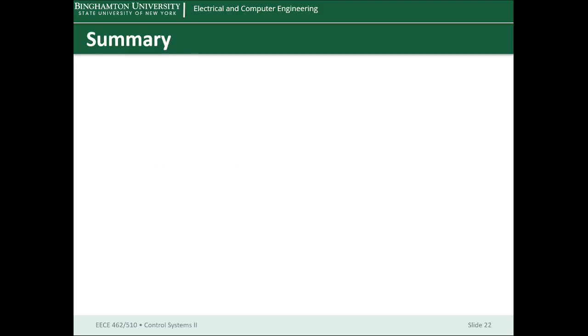Until now, we conclude we can convert every nonlinear tracking problem to a linear regulation problem. Then we can easily design our system based on linear control theory and use that for the nonlinear system.